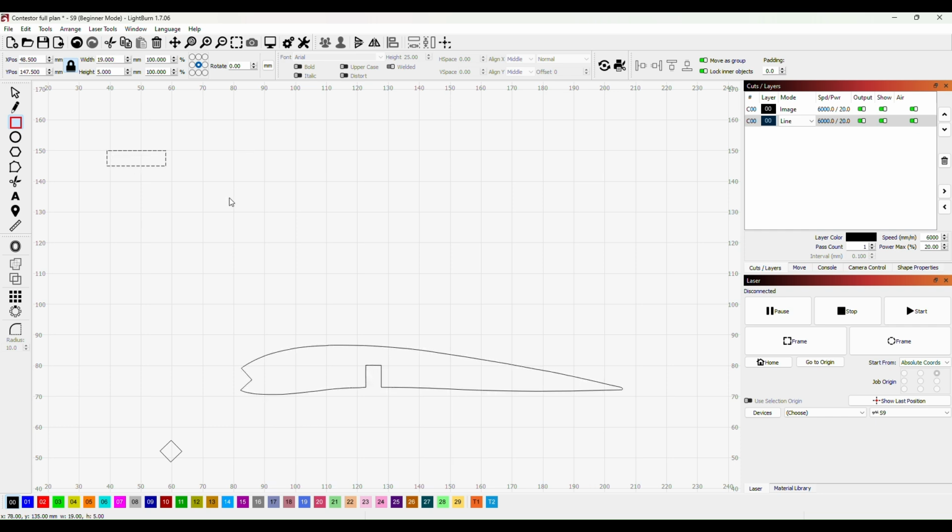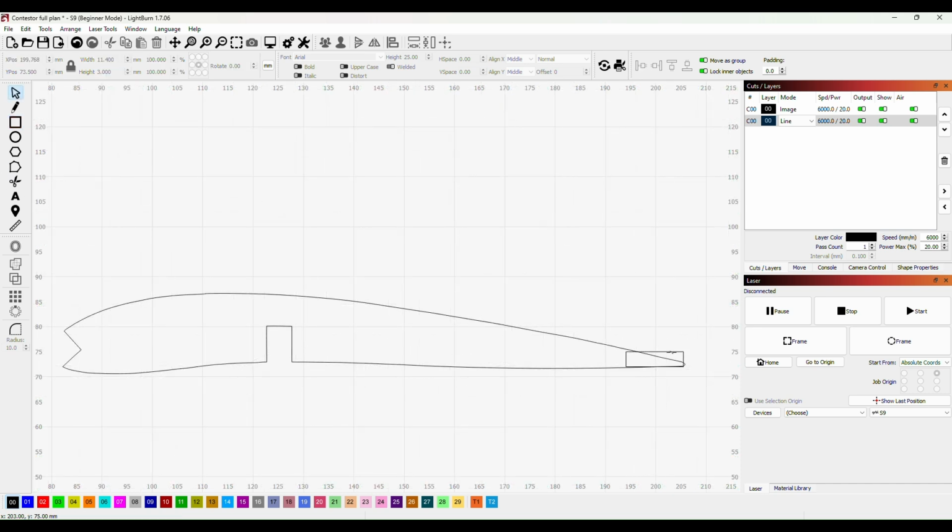What I'm going to do is do this same thing again. I'm going to make a shape. So I'm going to make this rectangle 15mm long, because I want to make my trailing edge 15mm. I'm going to make the height, let me say, 3mm. We've lost our sizes. I should have unlocked. I've made the rectangle, and I'm going to unlock sizes. I'm going to make it 15mm long by 3mm wide, which will be the size of my trailing edge. So I'm going to use a strip 15 by 3, and it's going to sit right there at the back